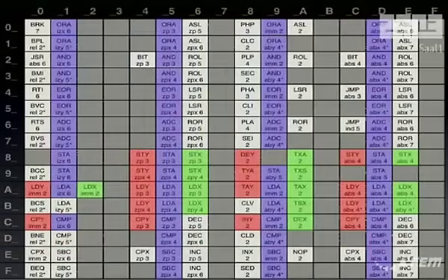And you can see this in the opcode table. The columns 0, 4, 8, C, and 0, 4, 8, and C are the ones that mostly deal with Y. All the ones that deal with Y are typically in those. And then the next column is all about A, and the other one is all about X. So it's all about the lowest 2 bits.